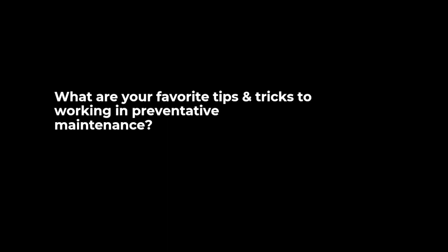So I would say the curve is very useful to understand which assets you want to place on that PF curve and say, okay, these assets are very, very critical for me, so I'm going to place them much higher on the curve, and these are the condition monitoring technologies that I need to apply to make sure that it doesn't go any lower on the curve with respect to failure, and I can catch them much higher.